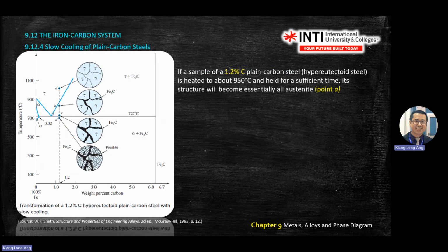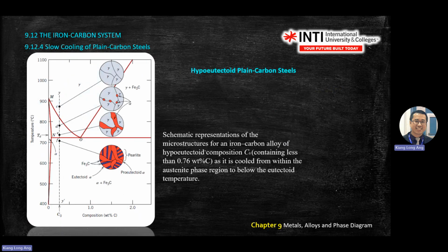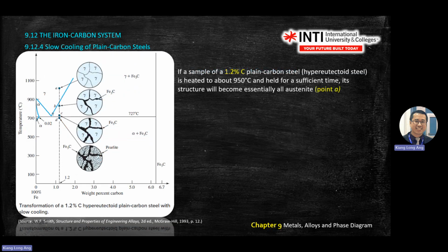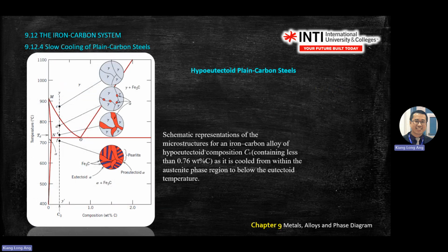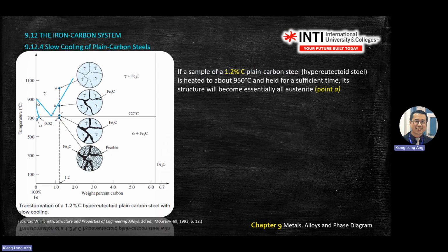Okay, so this is another one, same thing, just a different illustration. So if you cannot remember what is pro-eutectoid and eutectoid, you combine the two, you write pearlite, also give you correct one. You combine these two to become pearlite like this diagram, also correct. Again, important part, you don't draw it in the middle here, it grows on the line there.